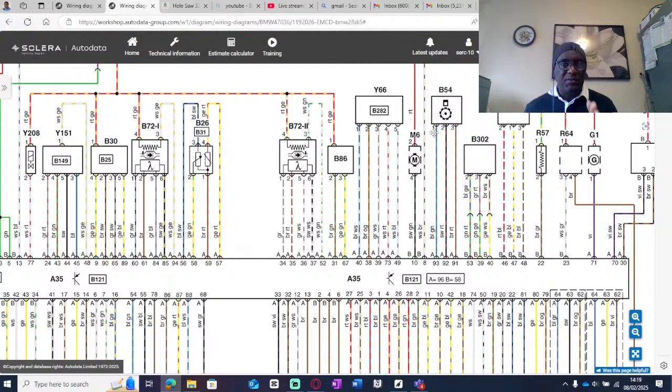You see me do test them in the videos, but when I need speed, I have shortcuts that I use, but you only do that with experience. Don't do it when you don't have experience. Check all 3 wires, record what you have, and then you can determine what each wire is doing. That's the best practice. Don't learn bad tricks from me.